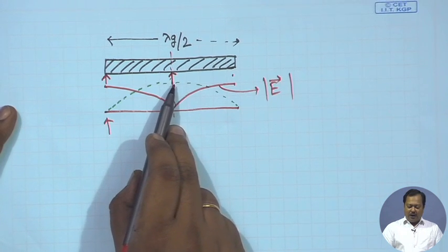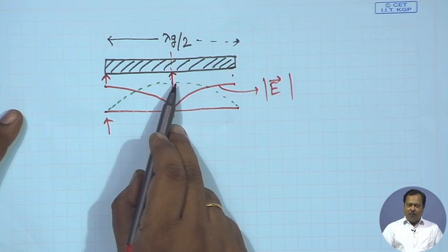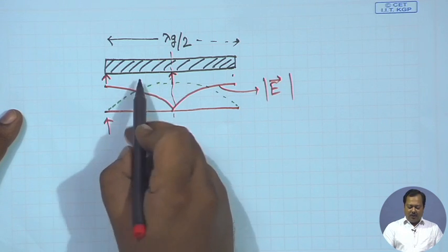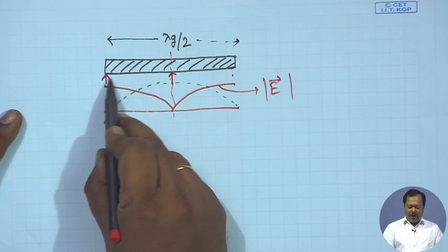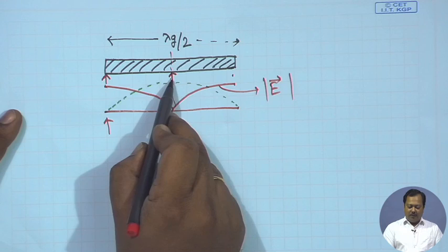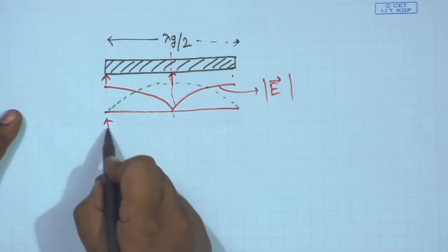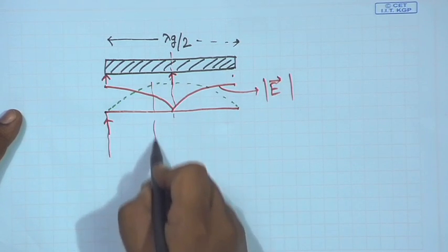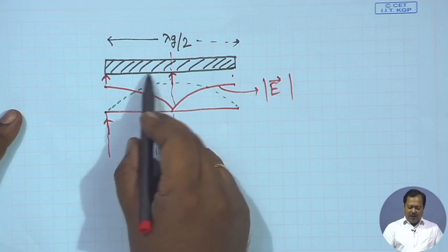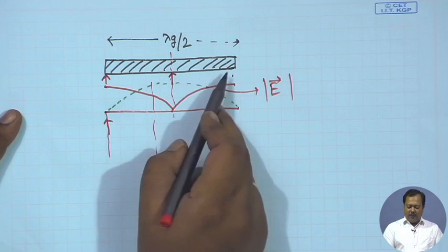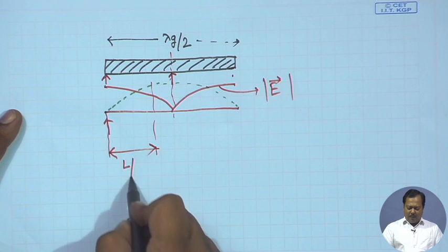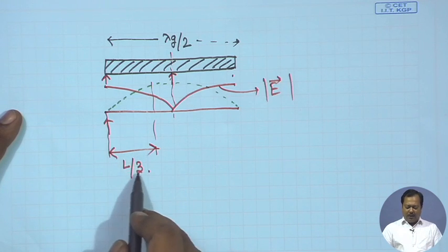For microwave circuits, mostly we use a 50 ohm system. So, for impedance matching, the feed point will be somewhere in between this z equal to infinity plane and the z equal to 0 plane, and the thumb rule is that you consider 1/3 length from the left hand side. So, if the length of this resonator is L, then we have to consider the approximate length from the left hand side as L by 3.